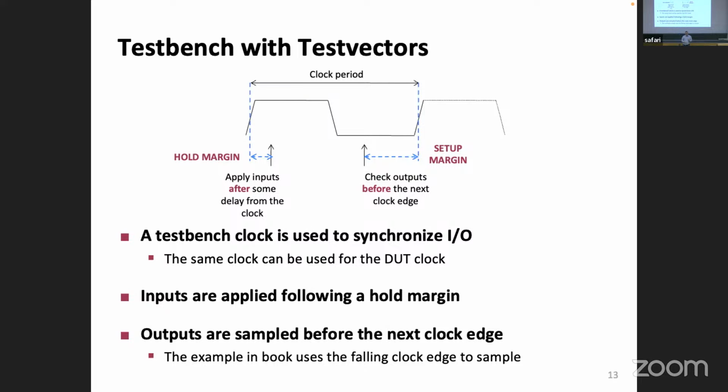The second problem is, while we are designing these circuits at the RTL level, when we are simulating it at the RTL level, meaning that this is the HDL code, we don't really have any delays. Things happen instantaneously. So there is nothing happening in the combinational logic. This propagation delay doesn't happen unless this thing is already mapped to a technology, to an FPGA, and has real delays in it.